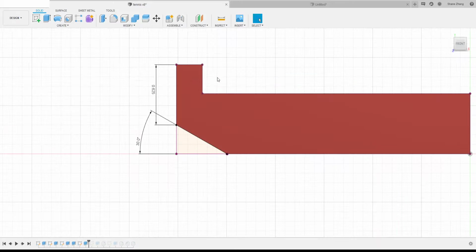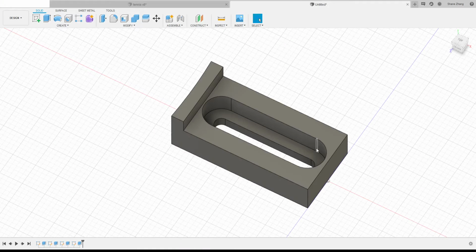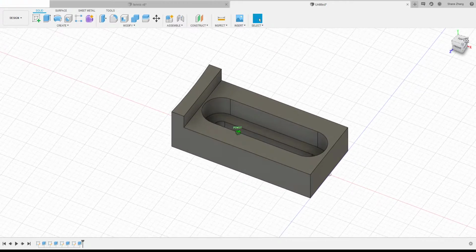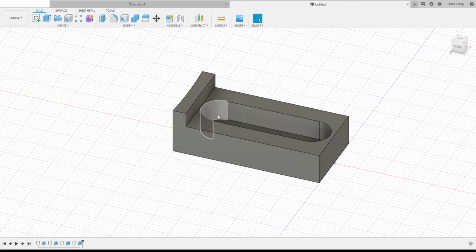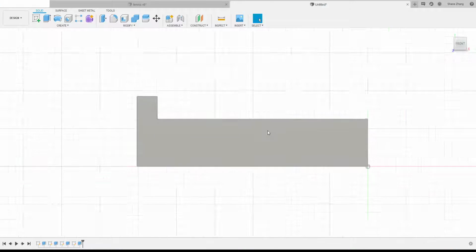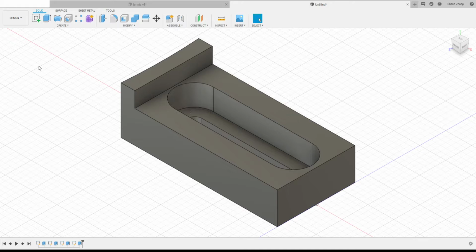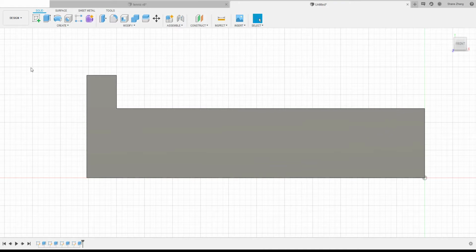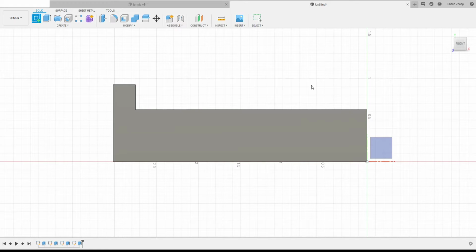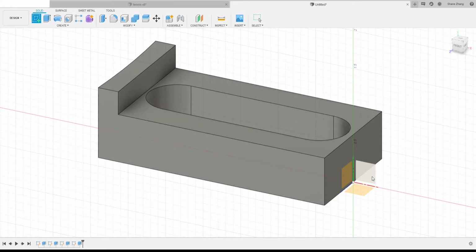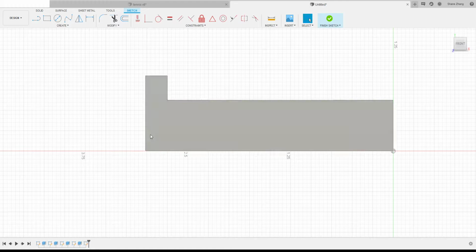Okay, so we're going to make another sketch and make the cut. This sketch is perpendicular to all the sketches we have done so far, and it is on the front plane. If you look at this cube here, the front plane is right in the middle, perpendicular to every sketch we have done so far. So let's try. All the named planes are here. Okay, so we're looking normal to the front plane. I'm not sure if Fusion does this. In some software you can pick a front and create a sketch. Here we still have to select. So basically front is this one, and we can create the sketch.